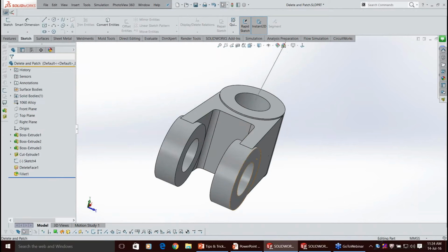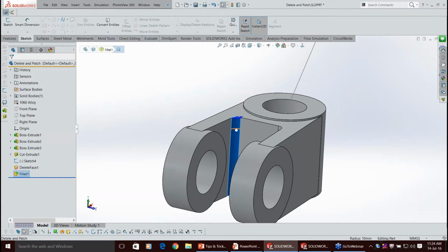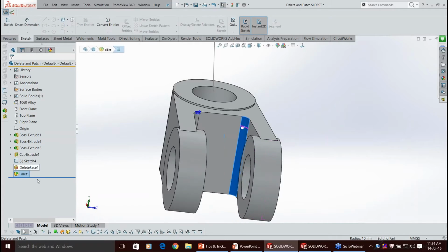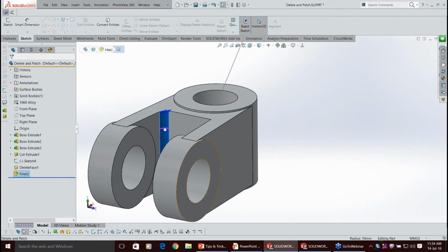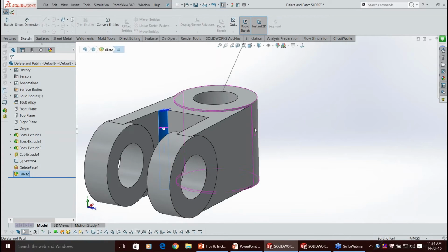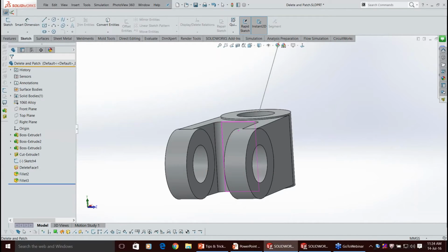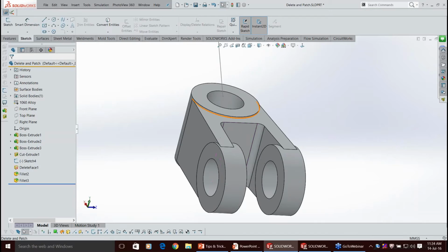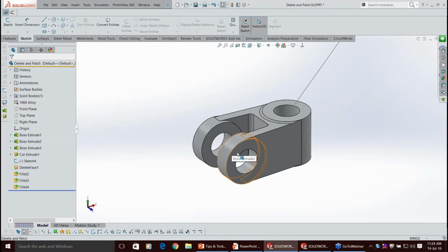One more thing is SolidWorks is integrated with Windows. I think you all know that. So everything like Control C, Control V works here. For example, I have a chamfer here. I have a fillet here. Wait, let me delete this fillet and explain it better. Now I apply the fillet only to one edge. I just select this fillet and do the conventional thing. Control C and Control V. See, it works. I think Control C, Control V we all are familiar with, and we use it quite often, so it will be useful for you inside SolidWorks also. Once I do Control C, everywhere I can just do the Control V and everything will be automatically taken. You need not select each and individual edge and say fillet again. So Control C, Control V works.